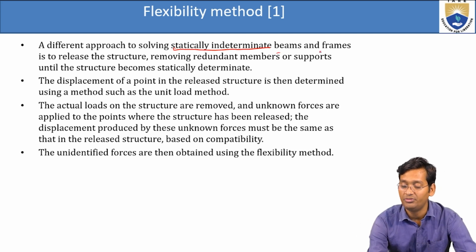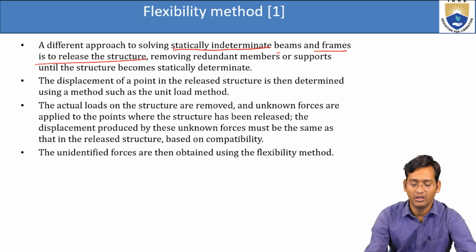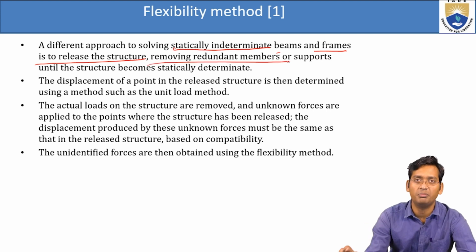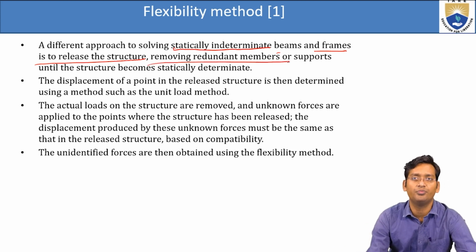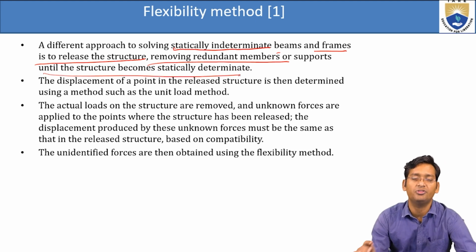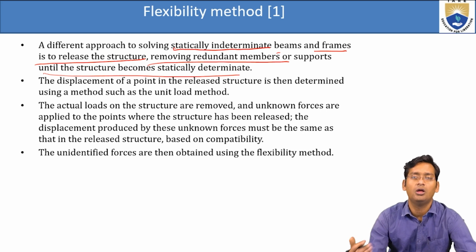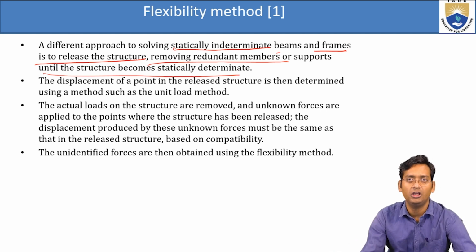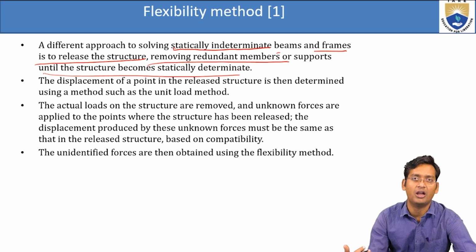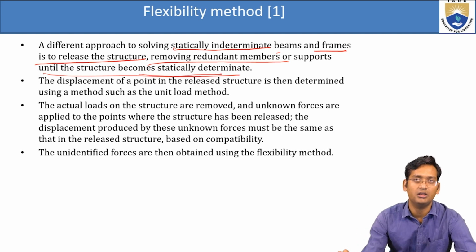For indeterminate beams and frames, you release the structure. Whatever the original structure is, release some members by removing the redundant members, or supports, until the structure becomes statically determinate. That means removing those members which do not distribute any load in that structure. Remove them till the structure becomes statically determinate.